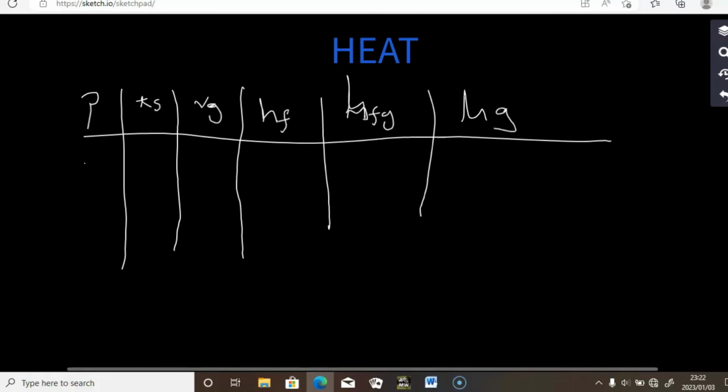So in this question, you are given what? The pressure. What happens is that we are going to have a pressure that we are working with. Let's say they are given 1400 as they did in this question that we are dealing with. So what you are going to do is go to the steam table, find that pressure, and then you can place a ruler.